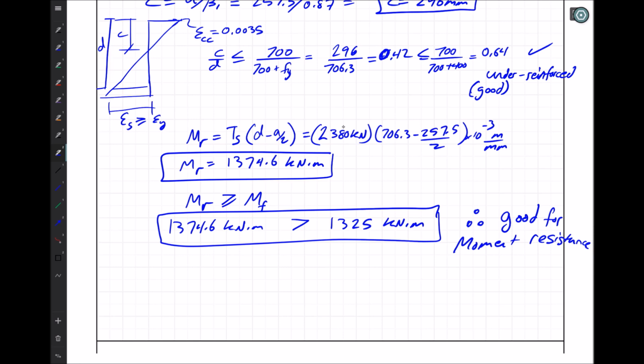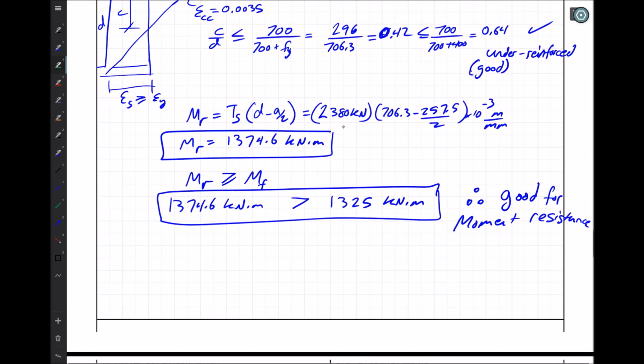Now, first off, let's just take a quick look at how good we did. We got it within a few percent of where it needed to be. That's excellent work. The reason for that is we didn't just take a stab in the dark and throw some random steel in there. We used the tools we had available to us in table 2.1, and we chose an estimate of size and then picked an amount of steel based on reinforcement ratio, and then worked off of that to try and design around it with a rational process that got us there, in fact, in one step.